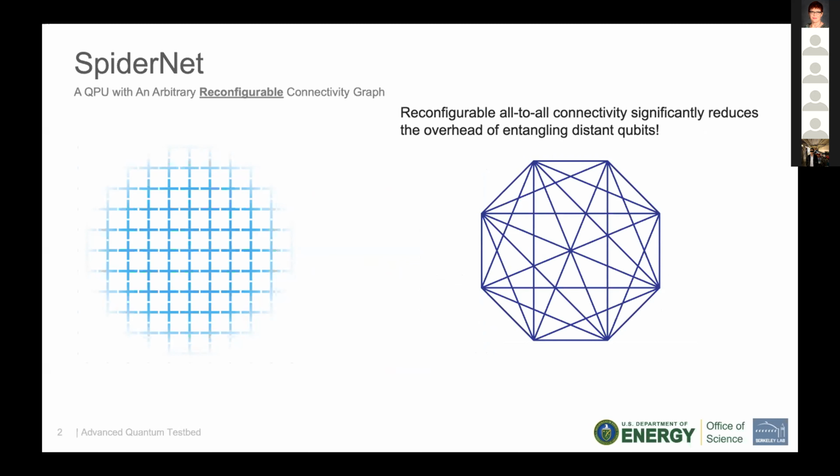And we do that, as I will introduce in the following slides, with an enabling technology that uses 3D integration to mitigate crosstalk issues and increase the controllability of individual qubits. This research is coupled with thorough finite element simulations that help us understand the electromagnetic environment inside this quantum processor and guide us to design the quantum processors in the best way.